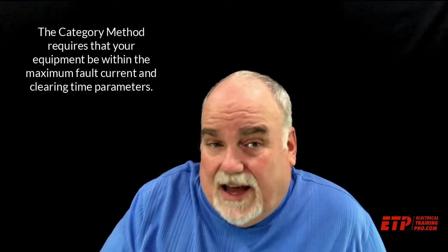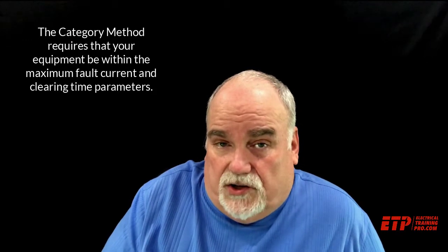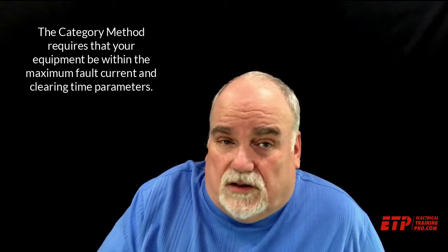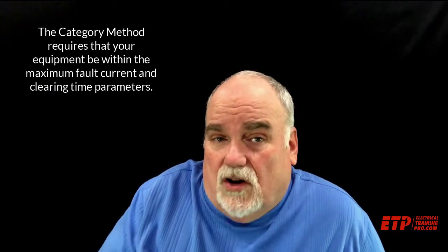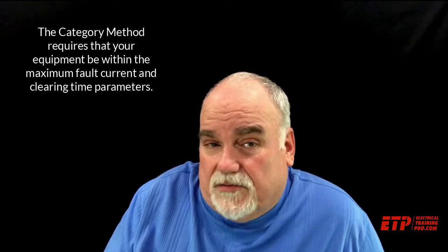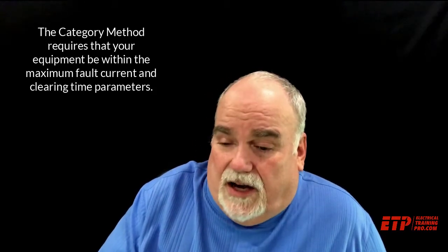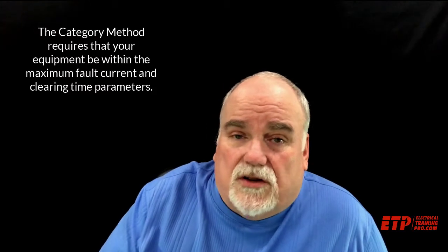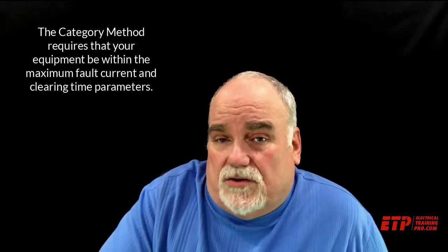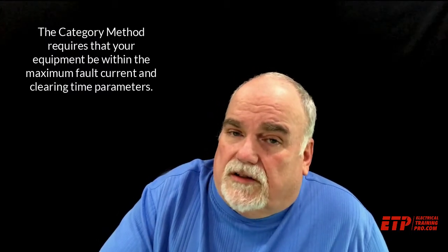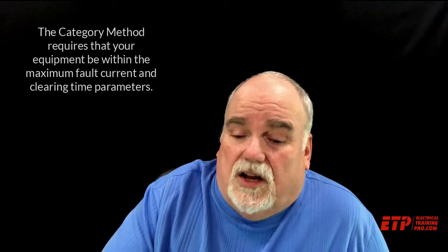So you have to put labels on even for the category method, because there are things that have to be evaluated to use the category method and have to be evaluated by engineers. There are maximum fault clearing times, maximum fault current allowance on the PPE tables. Well, for years a lot of people have ignored those, but we can't now. We have to have someone calculate those to make sure that we're within the parameters that allow us to use the tables. This is where a lot of people over the years have had to skip this because they just didn't have this done. But you need to have this done. The National Electrical Code now requires that you have maximum available fault current labeled on your service equipment. So we need to get this done.